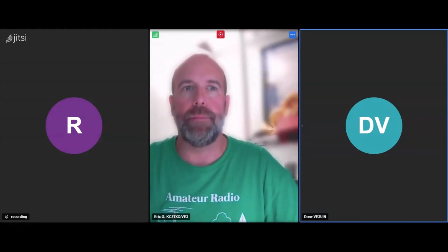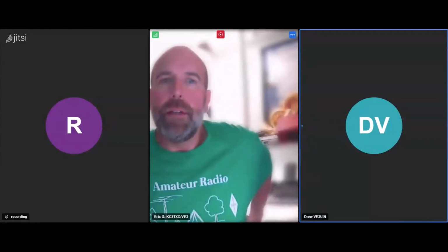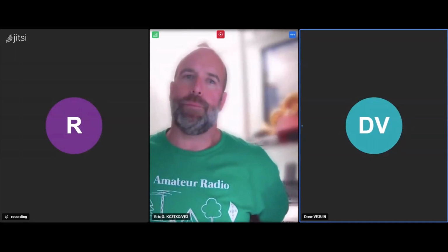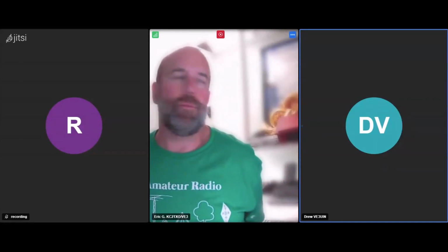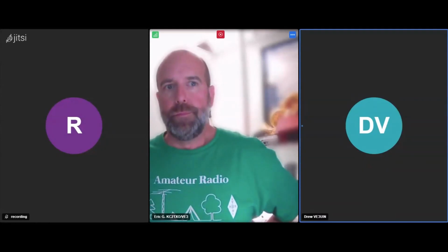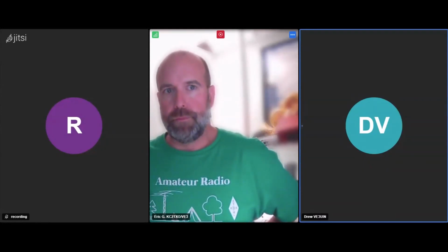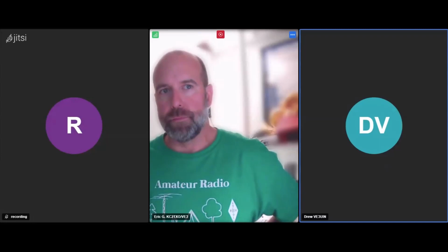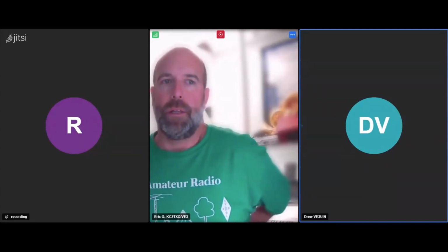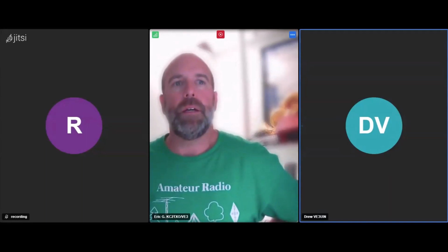They're very keen on that. There's actually a table of lengths to use that avoids it being an actual half wavelength. For the 9-to-1, you take 3 wires and you make sure they stay parallel to each other, and you wrap them 9 times. And then there's a nasty crossover thing. If I can find it, I've got the diagram for how you connect it.